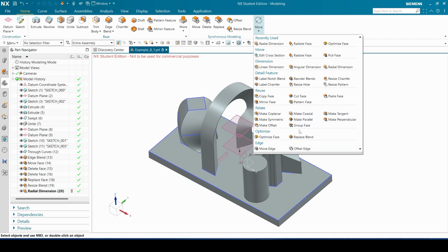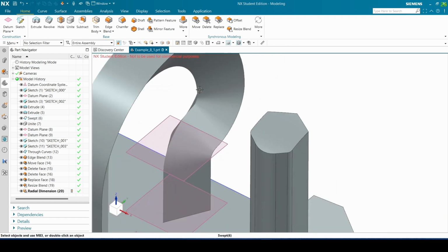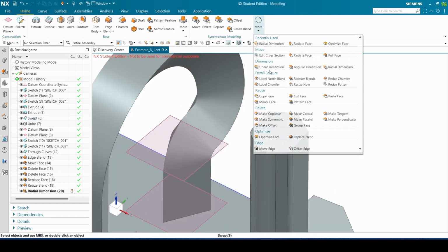One thing that you can also do is if you have a 3D model which is very problematic, there's a bunch of curves which it doesn't really interpret as curves, or it has difficulty figuring out what it is. It breaks easily. Perhaps even the model is not solid. Let's say, for instance, if this thing were exported and it broke, then somewhere over here there's an opening and now it's no longer solid. So then this optimize face will try to find all the different features and try to fix the part for you.